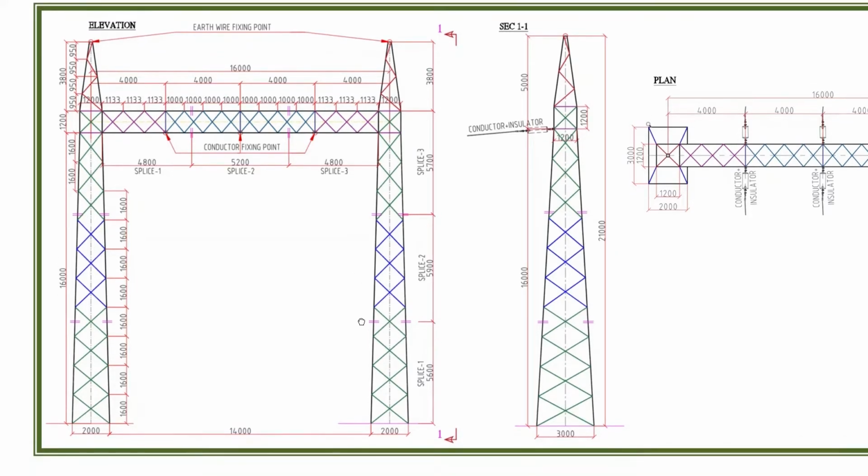Next, we need to segment the bracing member. In a tower you can see 2 or 3 colors are used for cross bracings. One is green from the base of the tower, another one is blue in the mid, next one is green again. In the top peak it is red. Likewise, we need to group the members which have similar physical parameters and loading parameters.